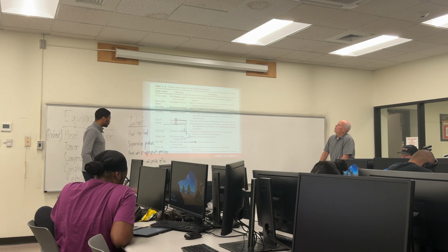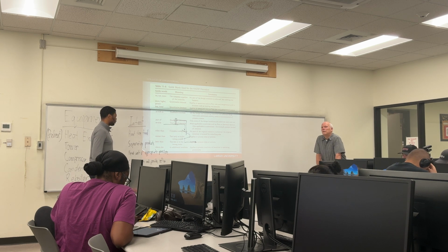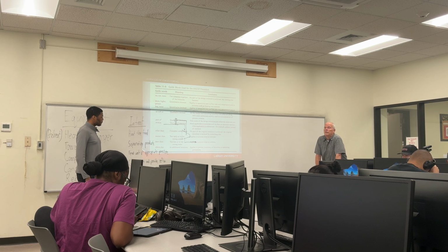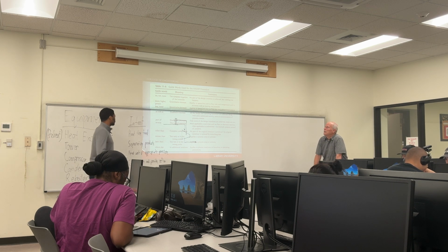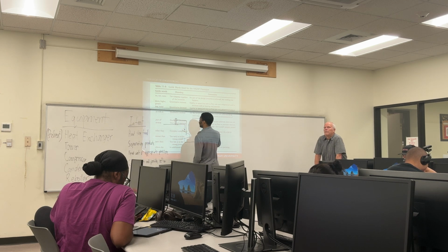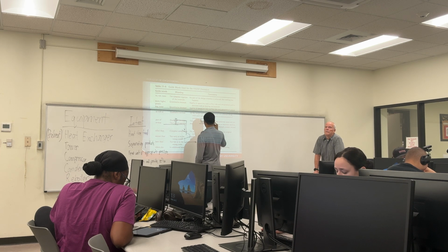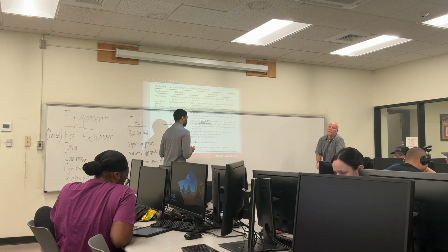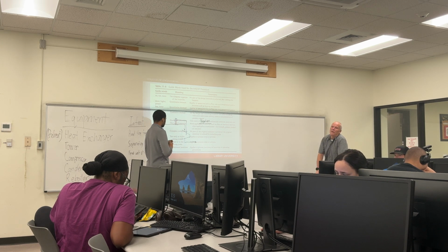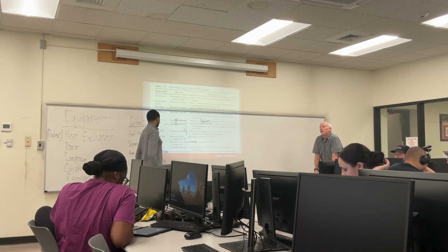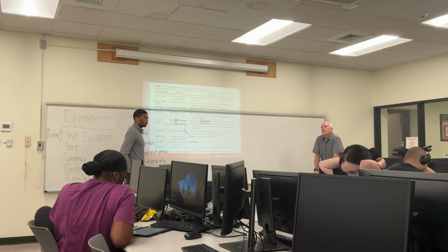Yeah, so what is the negation of the design intent? Compressor's just not working at all, just flow straight through it. What happens if the compressor stops? What if it doesn't achieve this? The outlet pressure is just the inlet pressure, so there's no pressure being added to the process. Anything bad happen? Products are probably going to be off spec. Well, yeah, it's going to be off spec. You're not making any product anymore. What else? What would happen if the compressor just shut down?